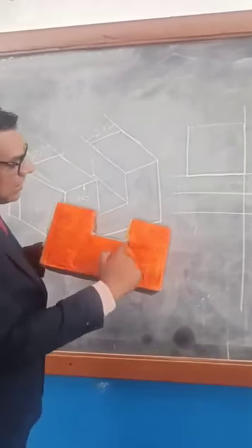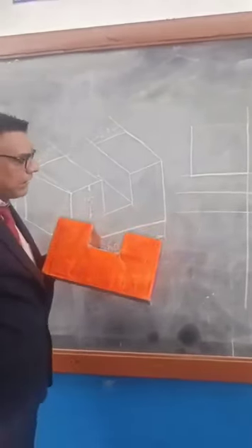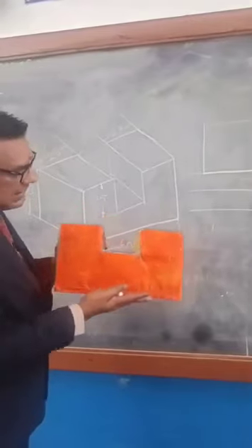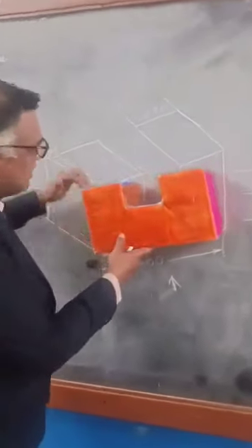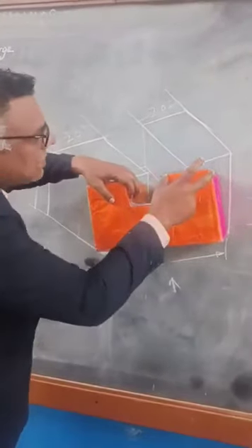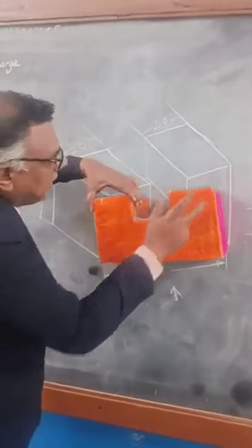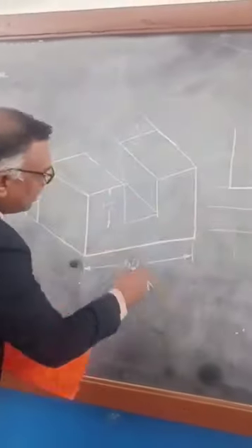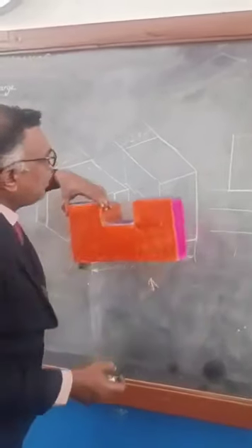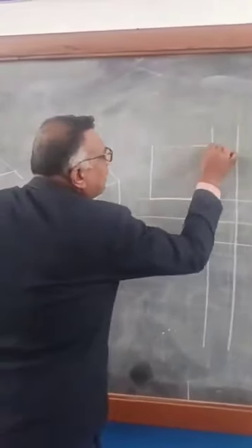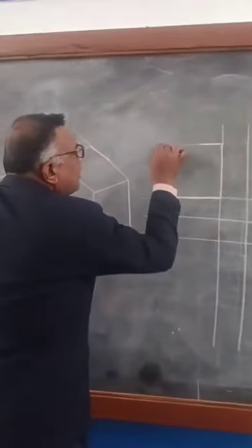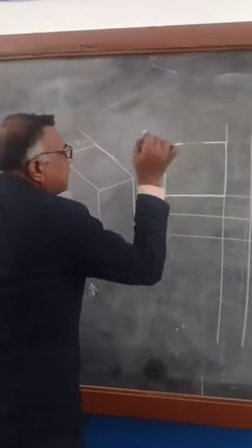Now I am going to draw a slot. So how to make a slot here? The total distance is 60. So this part is 20, and this part is 20, and this part is 20. So you get this total of 60. So now what you have to do? This is the inclined line. Make it a dark line for 20 mm. And similarly on the left hand side, make it 20 mm.